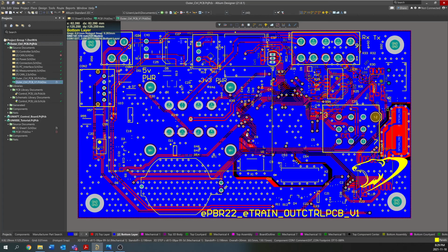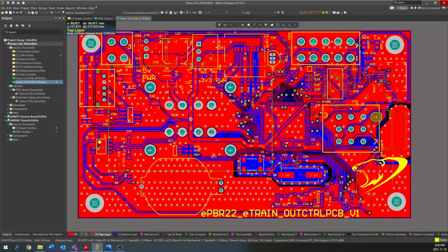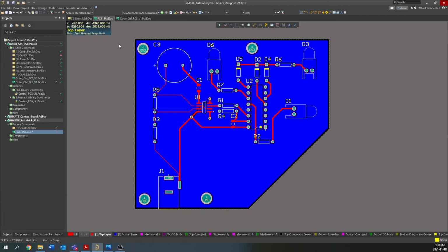At the end of the day, you might have some regions or some nets that actually don't connect, and those are called islands. You can either tell Altium to put copper there or not, and you might have to check if some of those nets are connected. So this is just an example of a more complicated board that you would do via stitching and a polygon on both sides for. Of course, the ground plane can also help with draining EMI and other types of interference.